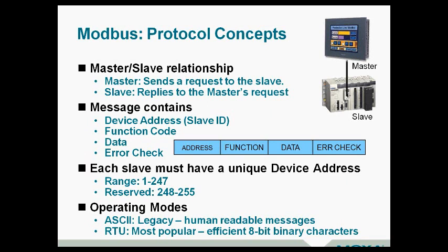Okay, so key concepts here: master-slave orientation, as we have with the HMI and the PLC in this. We have certain things that are exchanged. Each slave device has an ID, and most often folks are using Modbus RTU for what they're doing with that. Okay, good.